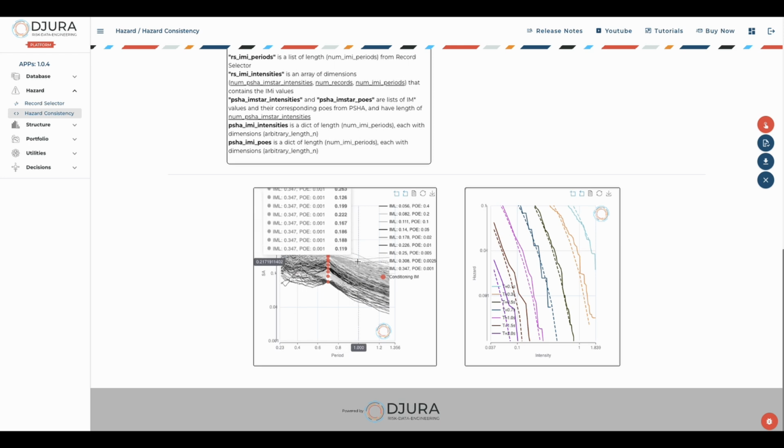You can see from the legend, it gets a bit crazy, but this is just because of the amount of information that's being plotted. What's the implied hazard of that set of ground motions with the associated return periods? So if I back calculate the hazard with those, what is the implied hazard at that period of vibration, so at SA 1 second? And it's essentially this solid line we have here.